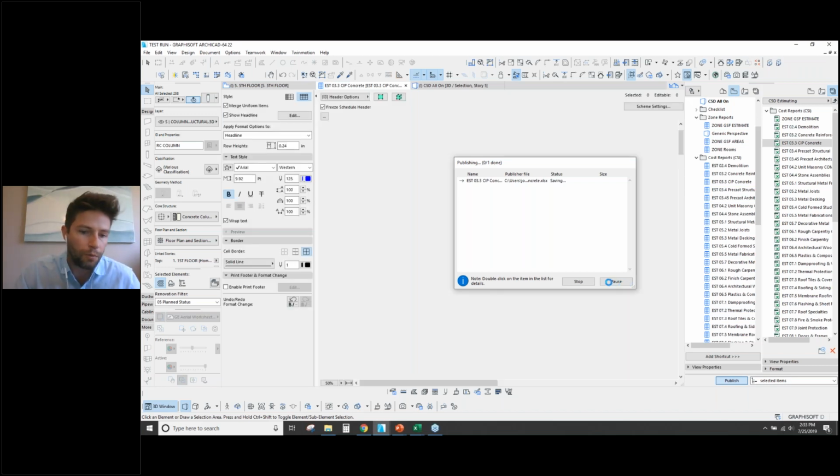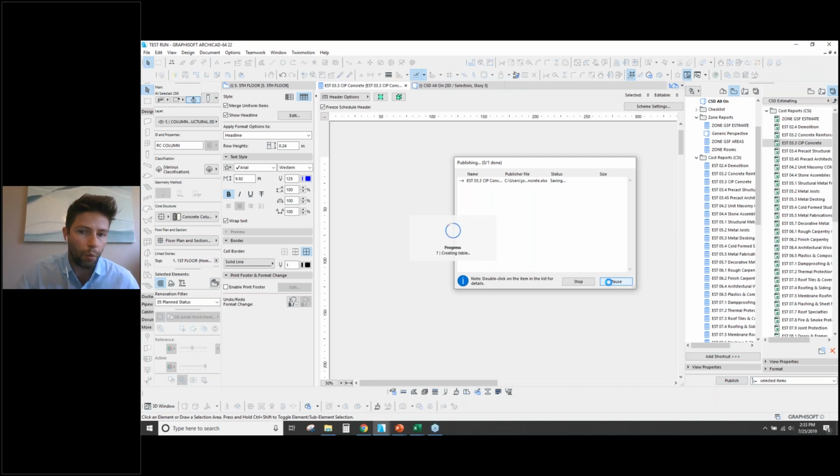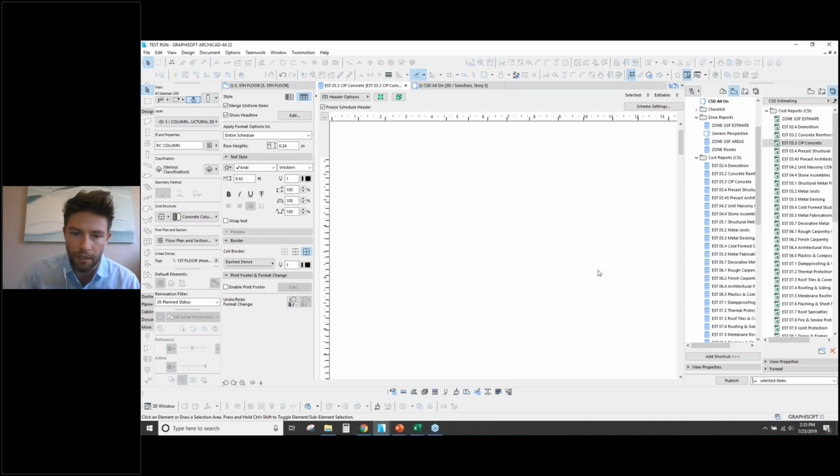So of course we can play with this. We'd probably want to bring in our concrete sub and get their input on what these values actually should be, or what it would cost for them to produce. And so just by doing this, it gives us another quality control tool to look at our quantities, make sure they're modeled in a way that's giving us good takeoffs.